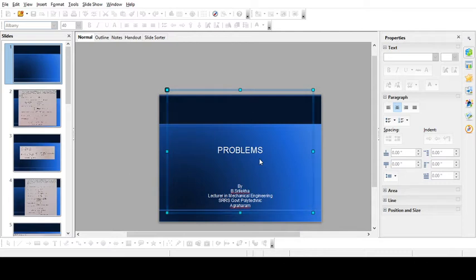Area of cross section is equal to, so given that the steel tube's external diameter is 18 mm and 12 mm internal diameter, and it is subjected to an elongation of 0.0045, and the load is 1.7 kilonewtons and the length is 75 mm.